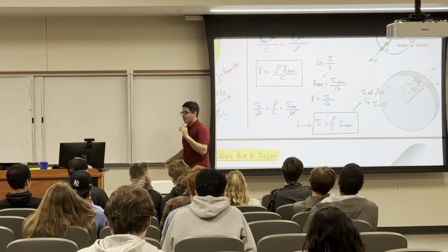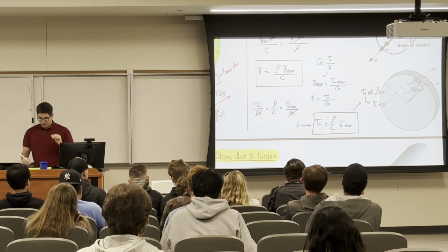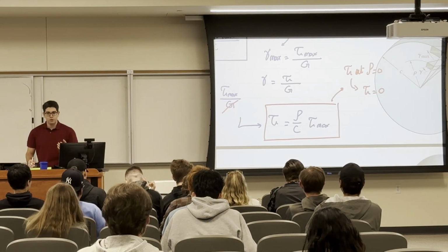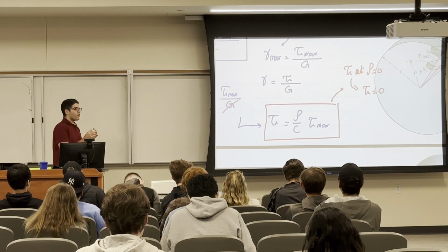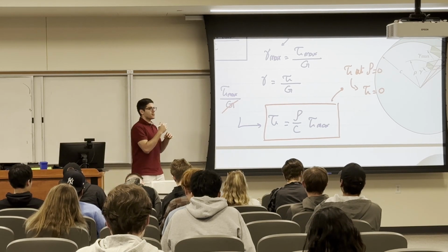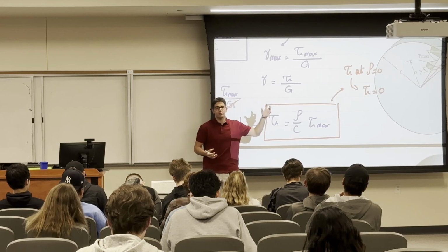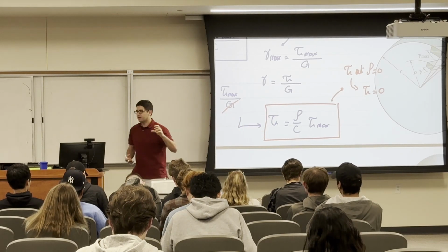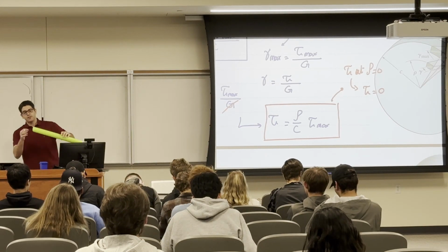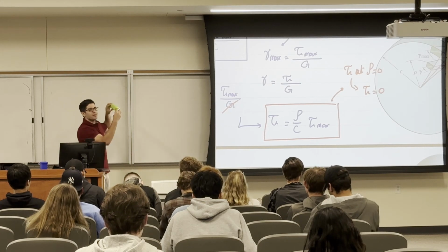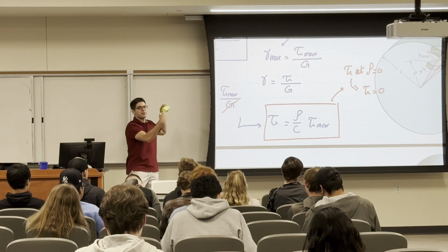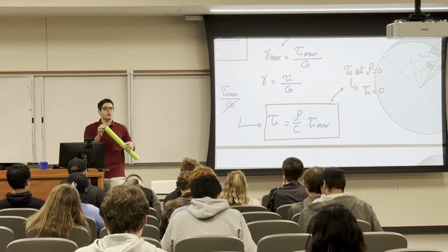And this is what we're going to play around with in a lecture about the moment of inertia. We need to find the places that have stresses so that we can optimize the material usage inside our cross-section. I can take the material in the middle out and put it elsewhere that's useful. In the middle, I don't have stresses.